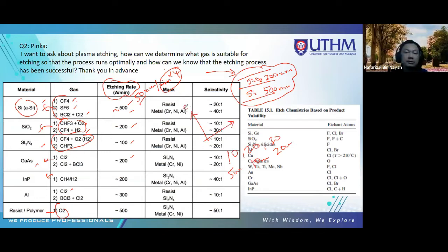So this is the etching thickness. This is the time. By having 10 minutes, I know one parameter. 20 minutes, I get one more parameter. 30 minutes, one more parameter. And then I can plot a graph over here. By having the gradient of this curve, I can know the etching rate, so how many nanometers per minute for my